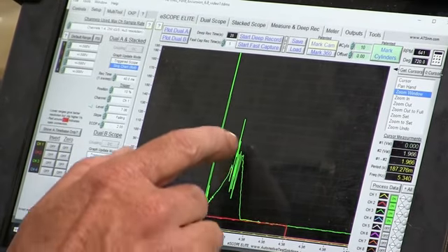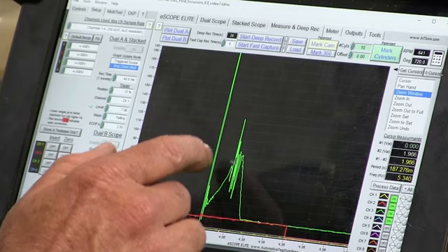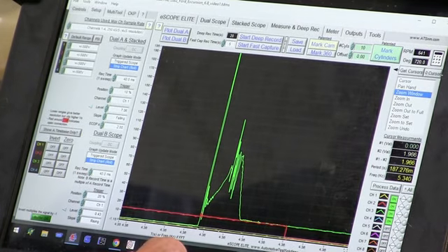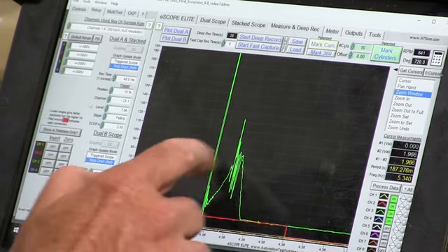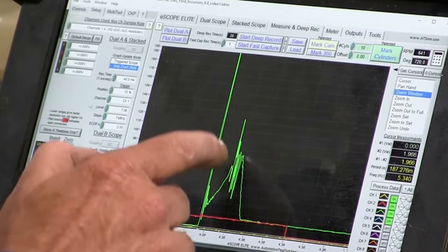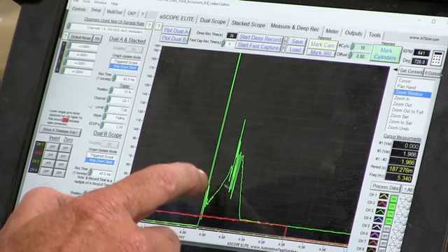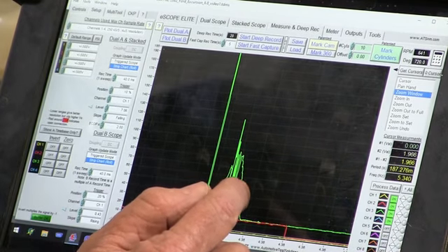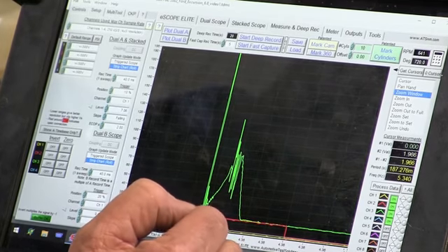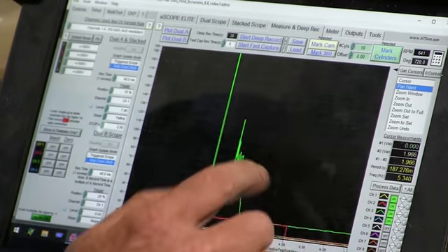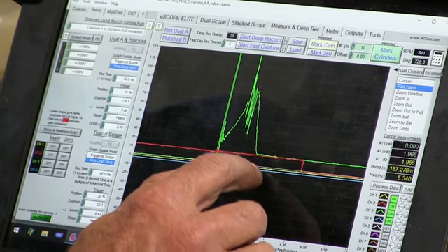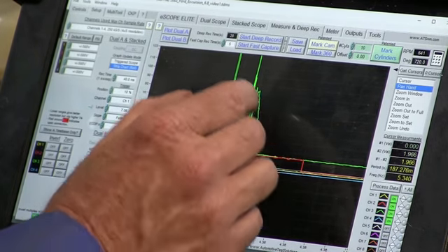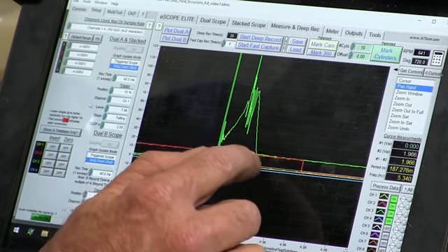Look at all this turbulent activity right in here. We snap it and we got a lot of turbulence. Now that might be some kind of a valve that could do that too, because I can get turbulence from being really lean, I can get turbulence from a valve, or I can get turbulence from a carbon trace. Now, the thing that makes me think different is I don't have a big tail on any of these. So I think that's some kind of a trace, and I'm dumping all my energy because I don't got a tail.